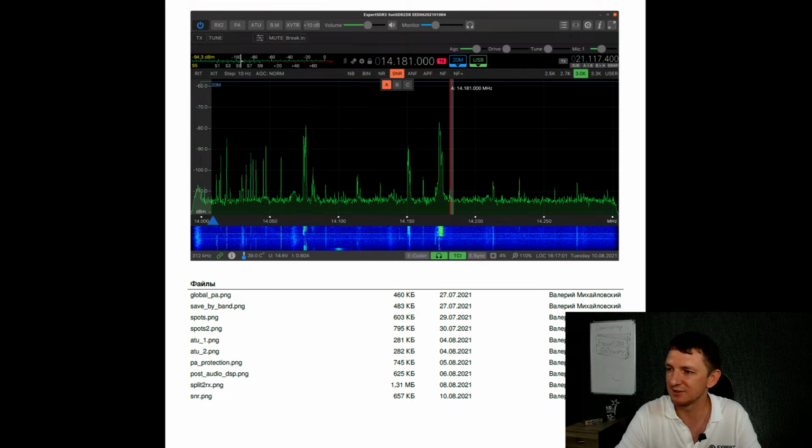And if any station at 65 megahertz, like broadcast stations, which are popular here in Russia, for example, or maybe some special stations, maybe military stations, transmits a signal at 65 megahertz, it will be received at the same time with the VHF band at 145 megahertz.